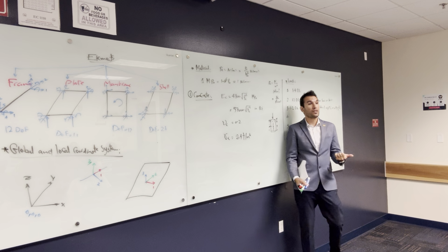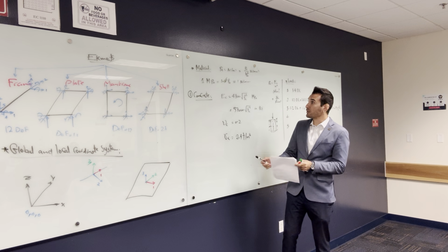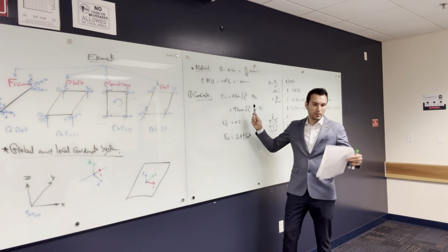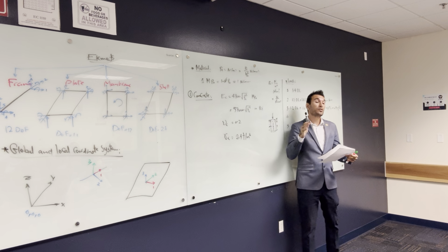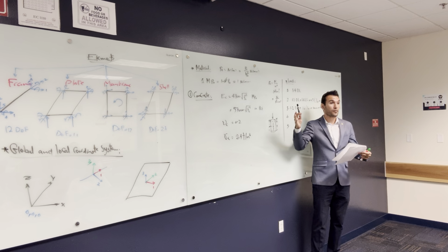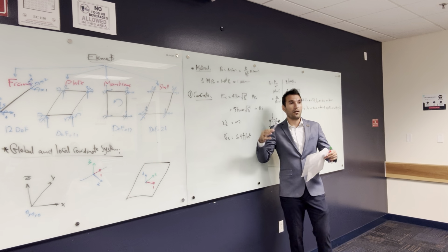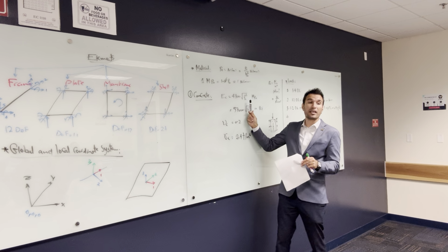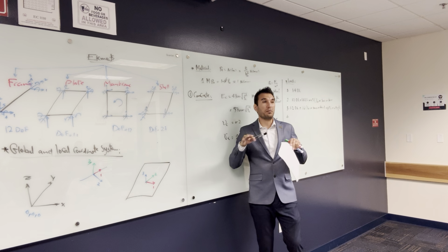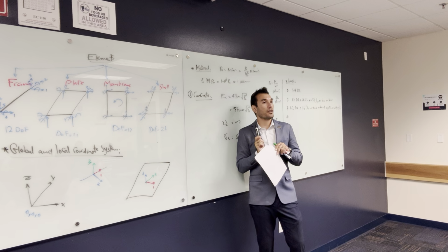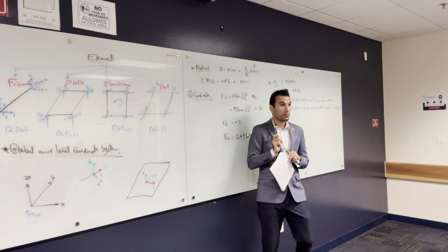So we usually use a high strength concrete or ultra high strength concrete. The normal FC is usually around 30 megapascal, but in columns, we use 60 and sometimes 100. We use concrete strengthened by fiber, very, very special concrete. So this number can be changed if you have a special concrete. But in our project, we're going to use the same concrete. Maybe we are going to use high strength concrete or something. So you have to define two types of concrete, okay?